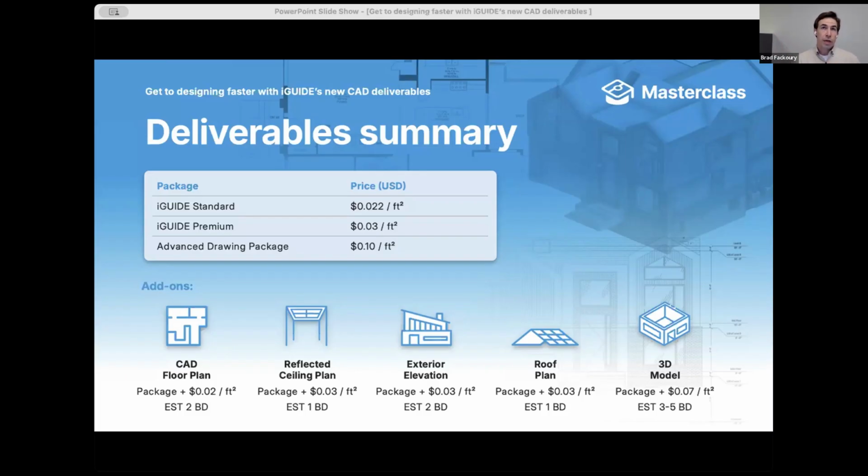What I traditionally do is put every single profile or building section that I'm creating with vertical scans on its own floor. It helps me keep the data organized. It helps our drafters keep the data organized, so it's easier to find the information they're looking for while they're building out the packages. So anytime I do an exterior profile or a site, or if I'm doing a slice of the building, I would have those on individual floors to keep it organized. We do highlight that in our knowledge base a little bit if you're looking at some of the advanced capture help, and we'll link to that after as well.